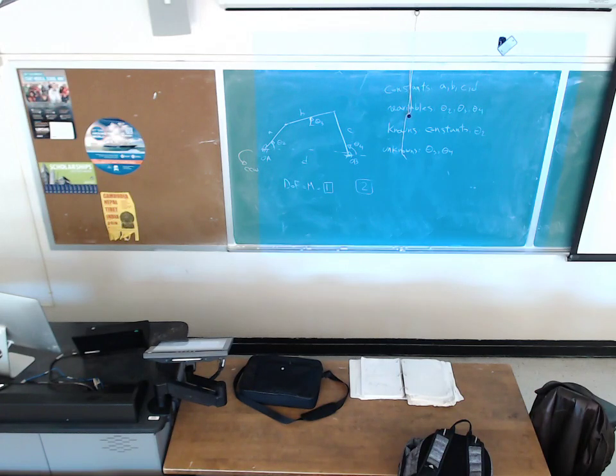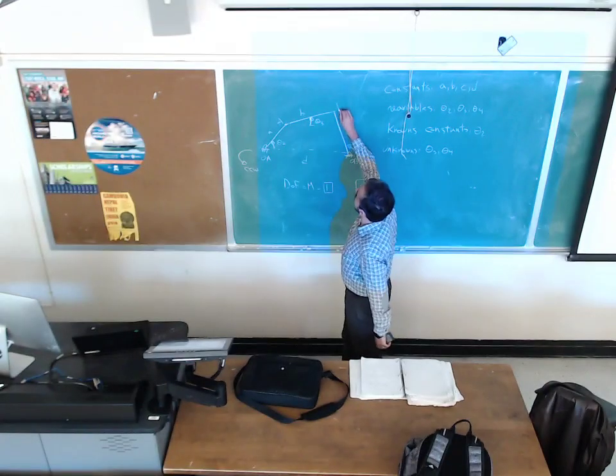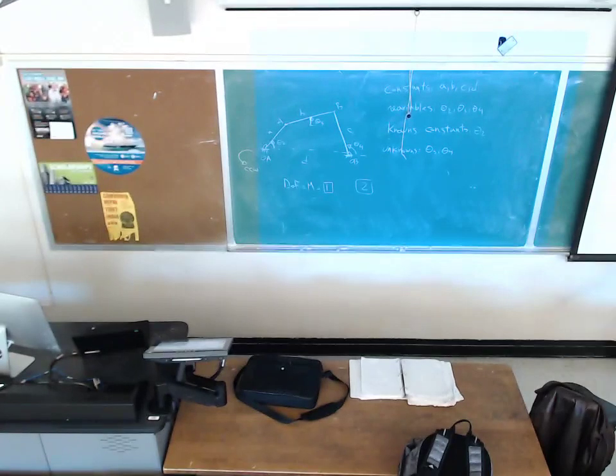Right here, draw a link with the angle of theta 2 from the graph, and find the location of joint A. This is joint A. So if I find the location of joint B, I can connect OB to B and A to B, and we are done with the graphical approach. After that, we can measure the angle of theta 4 and the angle of theta 3.